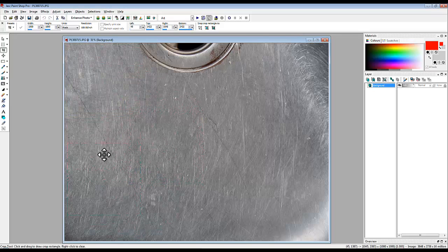Now, if you're doing this with photographs, don't tend to go for the edges, because there's this vignetting effect with the lenses, which means it'll get slightly darker even if you can't tell just by looking at it. And also I've photographed the inside of my sink. That's my plug hole there. Sorry, it's not very clean. And I've tried to get the grain of the scratches. So you see I have been cleaning it. That's Brillo pad action, running up and down, because I know that with the mirroring that'll be less obvious. So whatever textures you capture, if they've got any particular nap to them, make sure that you've got it running in that direction.